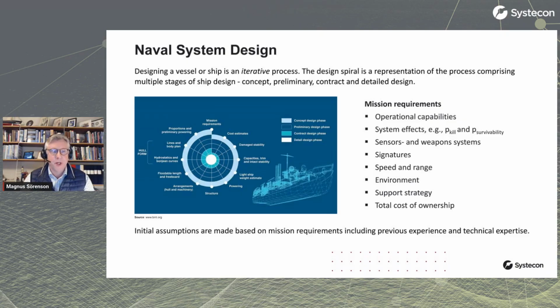Based on these requirements, you start to establish a certain size and proportions for your vessel. You need a hull form that can sustain the seakeeping capabilities you want and the speed and other comfort criteria. Certain propulsion: are you going high speed, low speed, operating in shallow water, etc., or do you have noise limitations? Hull material and structure is an important part. Maybe you want to construct a vessel out of non-magnetic material or other qualities that will decide.